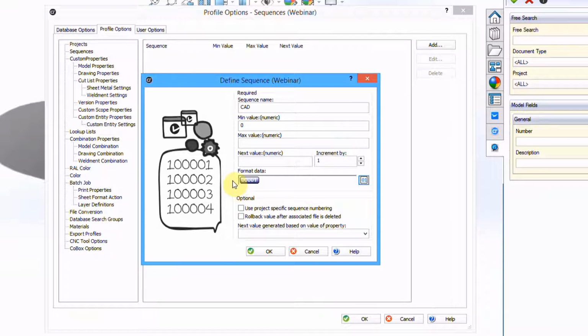You can use different properties in conjunction and concatenate them into a long string. So if you have a smart part number that's got a bunch of components to it, maybe some commodity codes and department codes, things like that, you use the combination properties to bring those together. So you'll first have to start with the model properties, set each component of that string to its own property, and then use the combination properties to put them together, and then create one more property to point to the combination. Right? That's the basic process there.